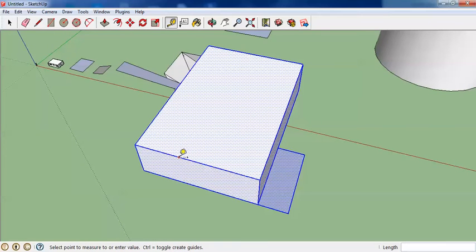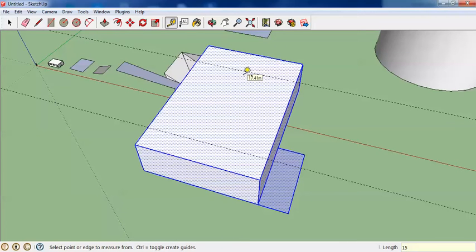Suppose I want to draw another line just 1 meter, or say 10 meter away from this point. Now here we have 10 meter. You can see the reference line, and this comes only when you press Ctrl and you get this plus sign just below the tools. Now select the point. Now make an offset how much you want it. 15 meter. Okay, here I go.